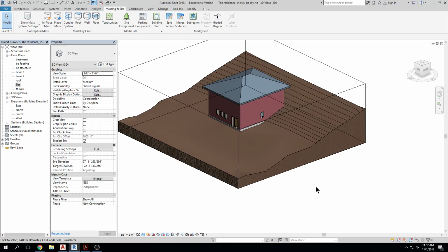So in SketchUp, it's made to create massing very quickly. So push and pull and move and rotate, those kind of things. It also has some artistic filters in it. So if you want to make this look hand sketched, or if you want it to look like you color penciled it, and you want to show a client a very loose rendering of your Revit model very quickly, right?